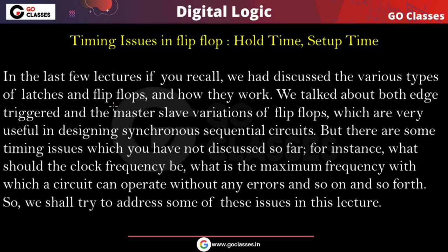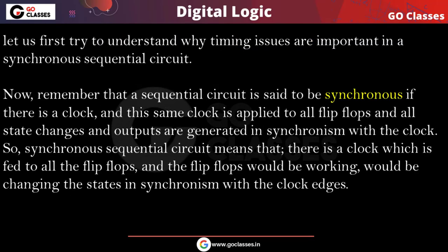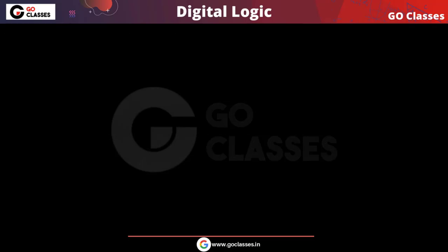We already know what a flip-flop is, what a latch is, and what edge triggering is. Usually flip-flops are edge triggered, and latches are level triggered. And we have already seen what a synchronous circuit is. A synchronous sequential circuit means synchronized with the clock, so remember the definition.